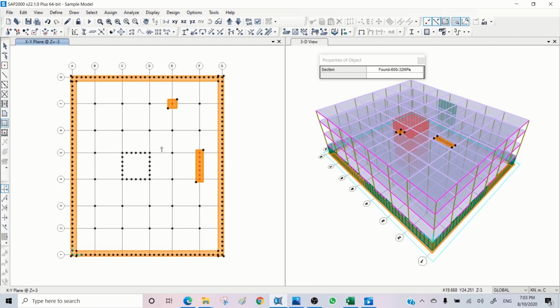So if you lower the shell to put the foundation in the right location, that means, for example, if the foundation for lift is say 800 millimeter, you want to lower it down 400 millimeter, you actually increasing the height of the wall 400 millimeter. So you don't need to do that. You just need to draw it 1.2 meters lower and keep the shell there. It's accurate enough for your design.